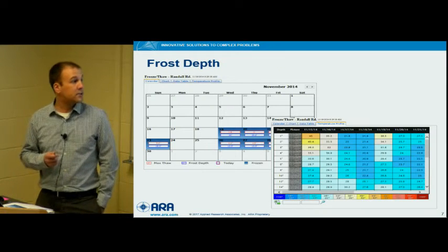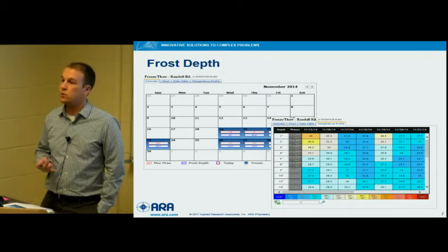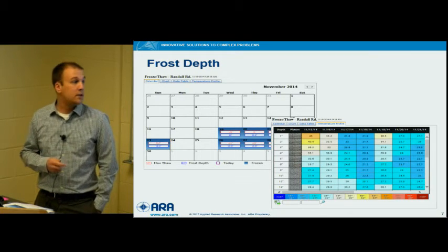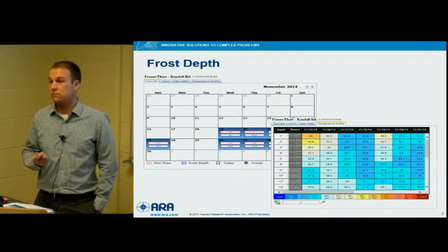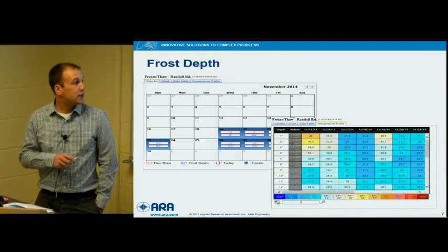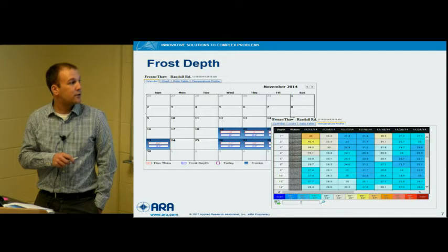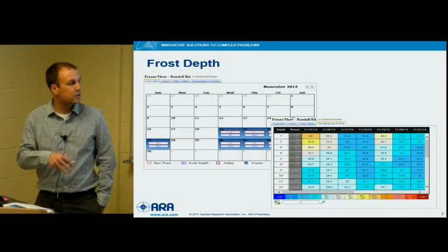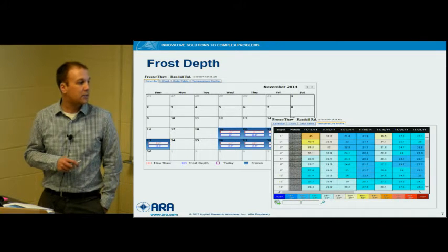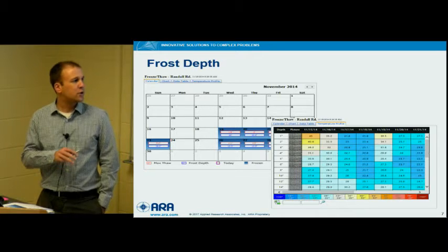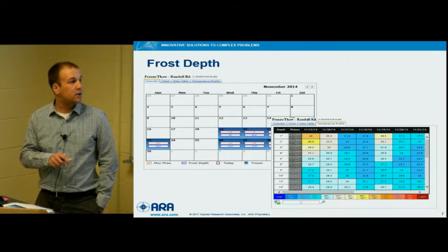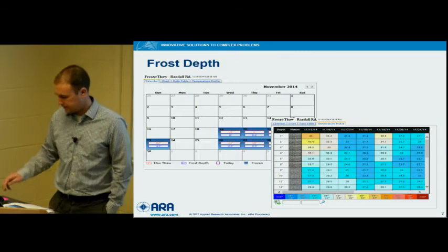And then the other aspect is, because the EICM gives you pavement temperatures with depth, you can see how deep your frost is and when your thawing starts. So it'll tell you here, the red is basically your thaw depth, and then you have your frost depth. So this is a fluctuation over time, and it can predict this fairly well. I'll show you another chart that's actually part of this when we do the demonstration a little later.